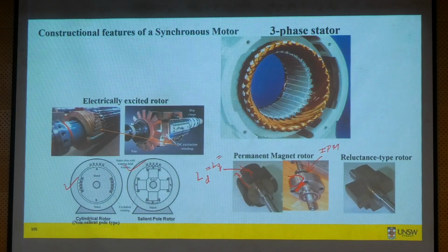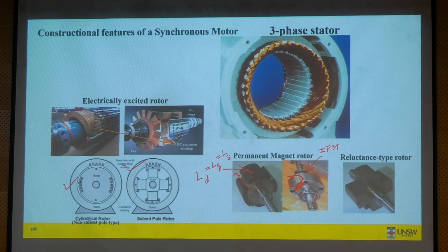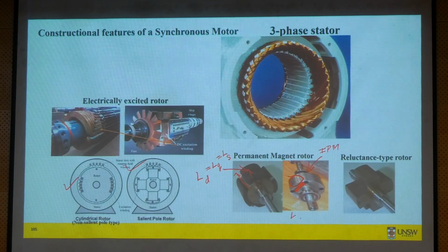And LD, LQ are synchronous inductances, okay? It is not self, not mutual, but synchronous inductance. And in this case, LD is equal to LQ. And here, LD is less than LQ. Okay?